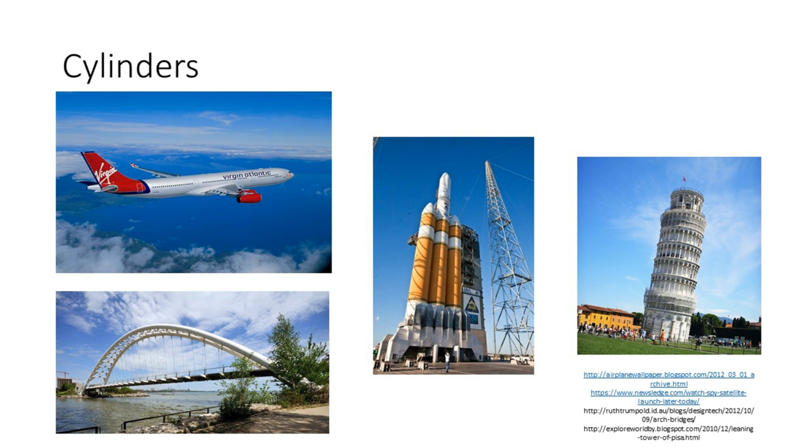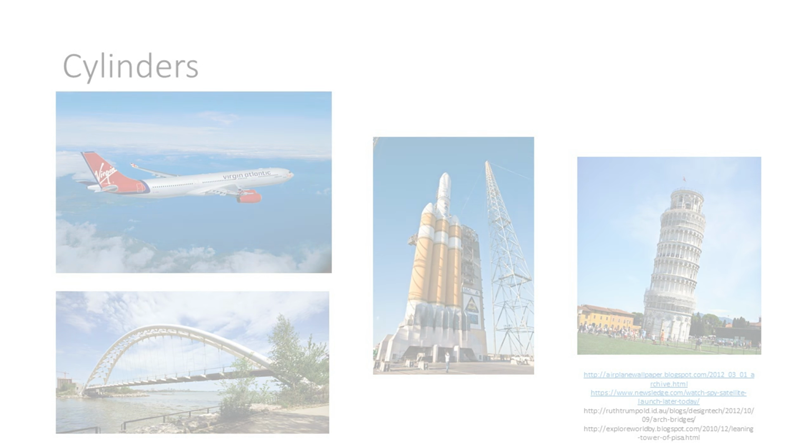Cylinders are an important object to analyze because they show up so often in real life. Cylinders are used for bridge pylons, bridge supports, rockets, hang glider frames, planes, and more. Studying the dynamics of flow around cylindrical shapes is crucial to avoid structural failure for all of these real-life applications. The separation point of these objects can be controlled with tripwires, circular wires, or sandpaper or rough materials.